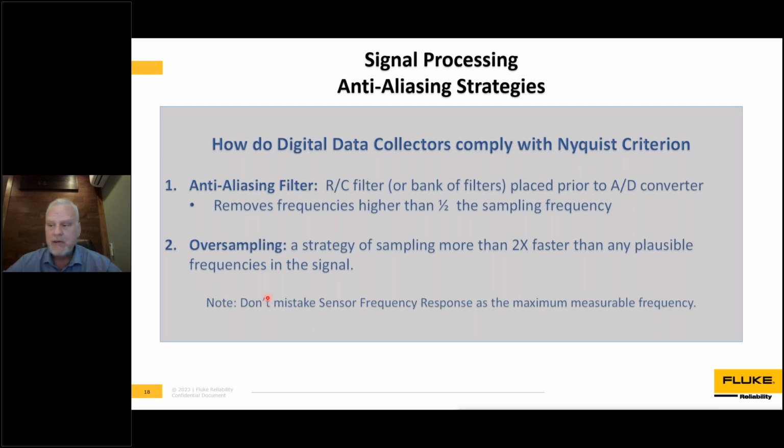They're there today, and as long as they're well understood and well implemented in your digital instrument, it's all behind the scenes. You're not even really aware this is happening if you haven't previously studied it. But it is super important to make sure these signals are pulled out of the signal before you digitize it. Otherwise, you get strange peaks in your spectrums that you're trying to identify that have no meaning to the actual running machine.